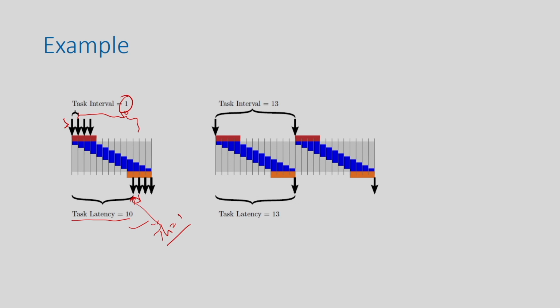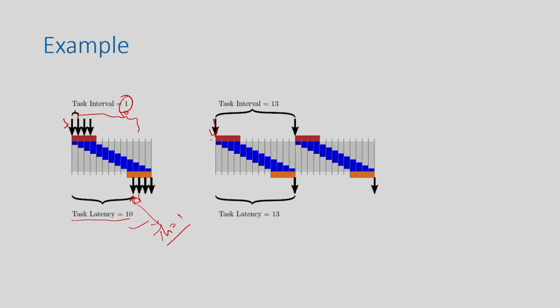Now think about the iterative execution of the loop. You give the first input here and get your first output here, and say you need some time to read and so on, so the total latency is 13 cycles. After 13 cycles you give the second input and get the output again, so again the latency is 13 cycles.